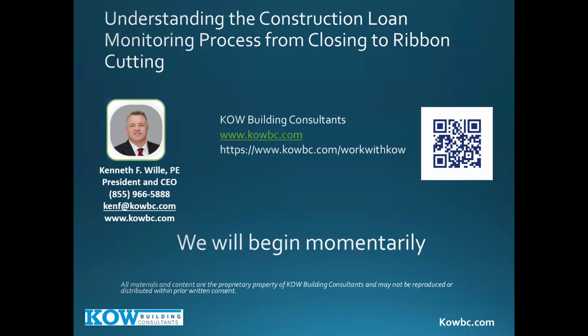Coming to you from our Midtown Manhattan office, a nice rainy day. Hopefully we're getting out of winter. A couple tips, actually, if you're coming out of winter with your buildings or your homes. One is check your skylights. You might have no drainage problems with horizontal water, which is rain, but vertical water is different, which is snow and could be an ice shield back up into a flashing or a skylight. So check that if you've had a lot of snow like we've had here recently.